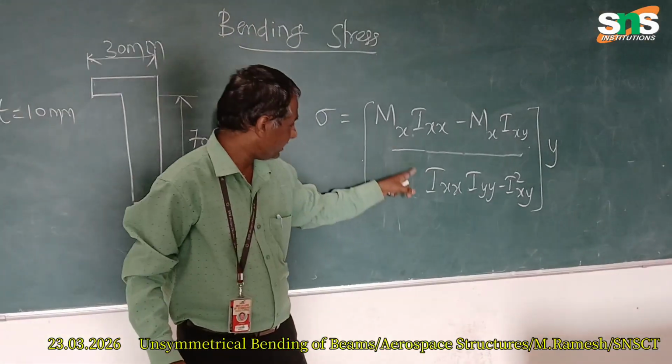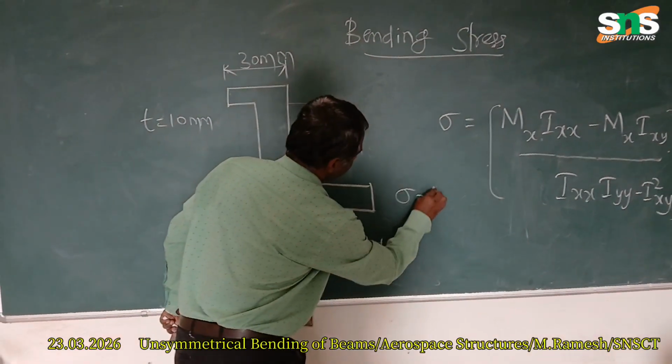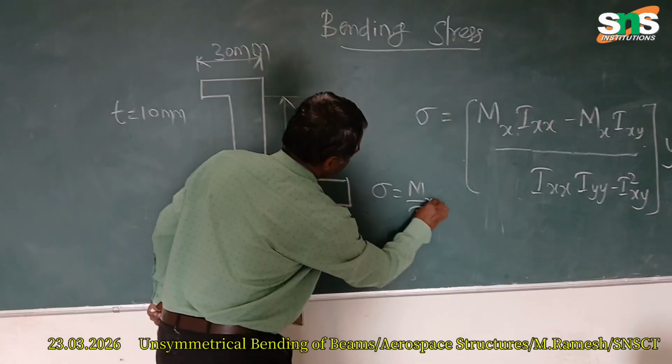That is nothing but M by I into y. So bending stress sigma equals M by I into y.